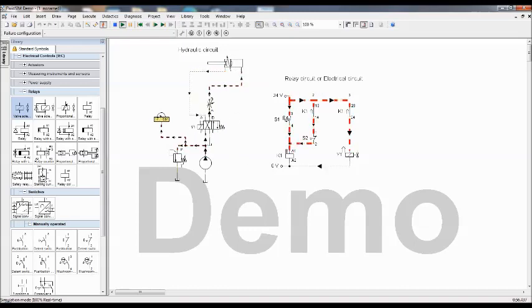See, now once S1 is operated, the cylinder is extended. You can observe here that solenoid Y1 is continuously on. So that means by operating the S1 switch once, the cylinder is continuously working on the load, maybe for example closing the door or pushing the load. Once work is completed, how can I retract the cylinder? I can operate the switch S2. Yes, it is retracted. So this is a signal storage.